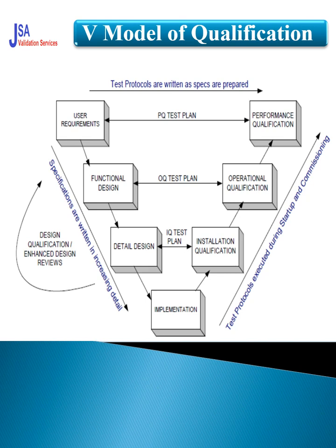Then come to the performance qualification. Performance qualification is the counterpart of the user requirement specification. What is our requirement, like how much pressure we require, what is the quality of air. ISO 8573 is the guideline for the quality of the compressed air.